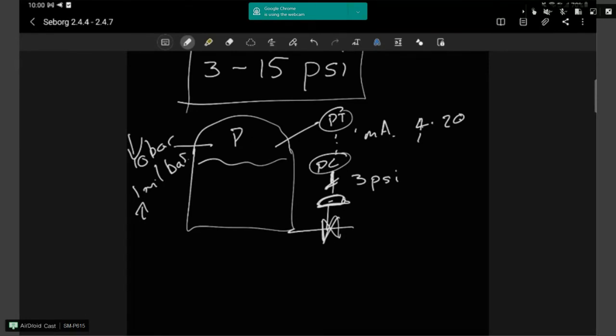The pressure that I'm talking about is this signal that comes in here. You'll see this black line here is a diaphragm, and in this portion there's a spring that provides force for pushing it down. When you provide that standard pressure signal, it pushes the diaphragm up, which extends this and opens the valve.